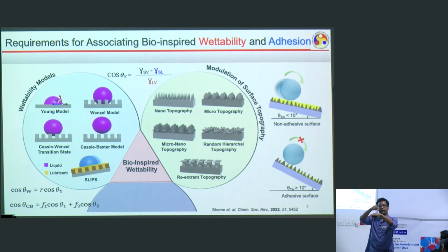Once it's in contact, you measure the contact angle, and then there is a pump, so you can recede the droplet back. Not pulling up, it's just motorized, you are sucking the water droplet, and at the point where it detaches, you measure the contact angle. This difference is called contact angle hysteresis, the difference between the advancing contact angle and the receding contact angle.